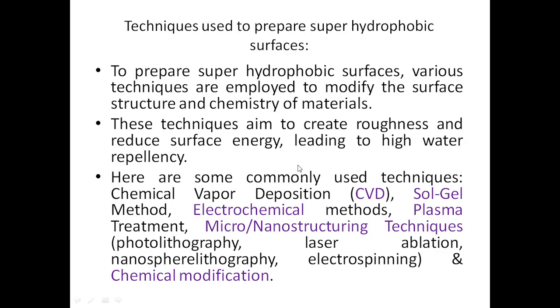This is also a deposition technique where you have a substrate and you keep on heating it so that the molecules will evaporate and go and sit on the cold film, which can be removed later and it will form a layer. Next, the sol-gel method, where the solution will be converted into the gel form, followed by nanoparticles. Then those nanoparticles can be used for the coating purpose.